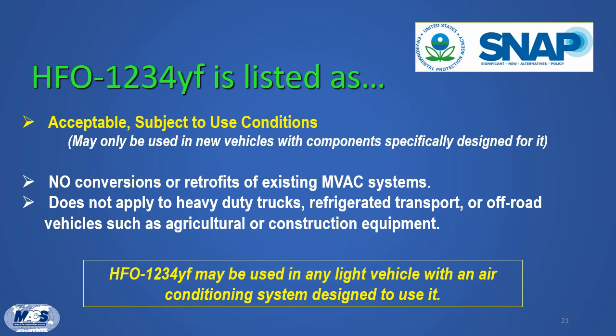So just for example, if you have a 2009 Ford that originally came with R134A, then you're not allowed to take that 134A out and put R1234YF in. Now, likewise, if you have a 2016 Chrysler product that came originally from the factory with YF, it's against the law to take that YF out and recharge that system with R134A.